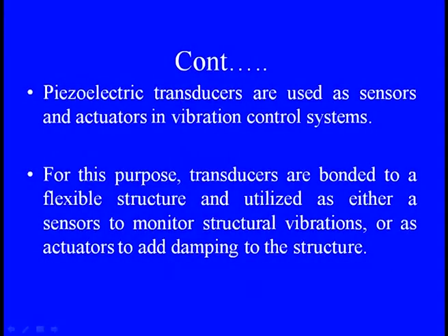So, these transducers act as a sensor or an actuator, and we need to see what kind of applications there are, because these transducers are simply bonded to the flexible structure and can be utilized either as a sensor to monitor the structural vibration, or as an actuator to add damping to the structure. This is the beauty of this piezoelectric device: if we want the sensing feature to monitor the structural movement, they can provide significant information. And if we want them to act as an actuator to the structure, they can certainly provide, through their reactive forces, this kind of damping to the system.